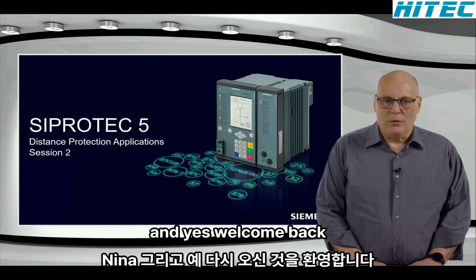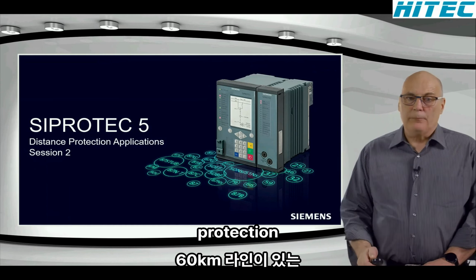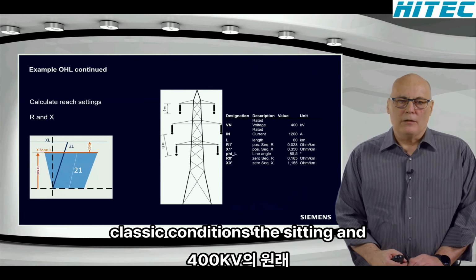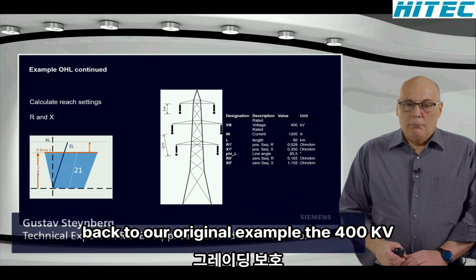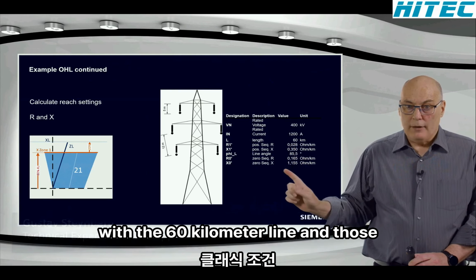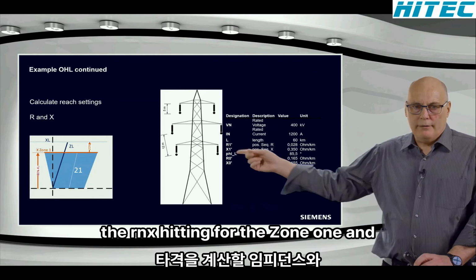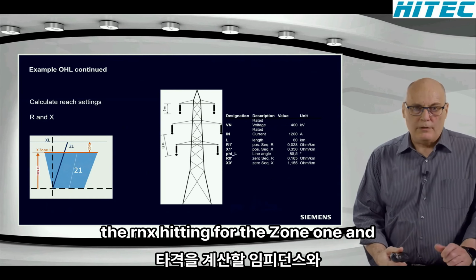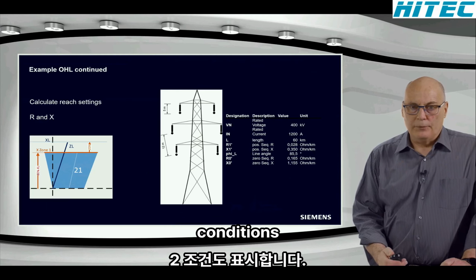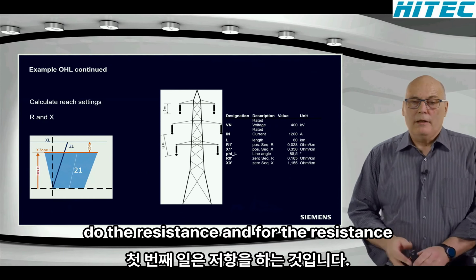And yes, welcome back. Now we carry on to distance protection classic conditions, the setting and the zone grading. Back to our original example, the 400 kV with the 60 kilometer line and those impedances. We are going to now calculate the R and X setting for zone 1, and later on also show the zone 2 conditions. So the first thing we're going to do is the resistance.